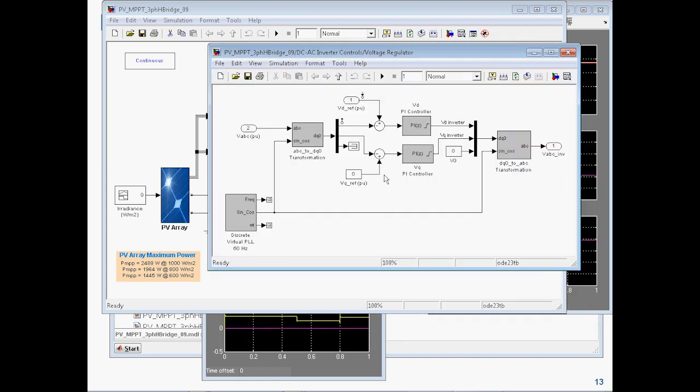When you're dealing with 3-phase systems, there's a slight additional operation that you need to do. It's hard to control the 3-phase sinusoidal, so what you do is a coordinate transformation. From ABC, you move to direct and quadrature currents. So there's an ABC to DQ transformation, and then once the controller is done, you go back from DQ to ABC. All of these blocks come with the tool.